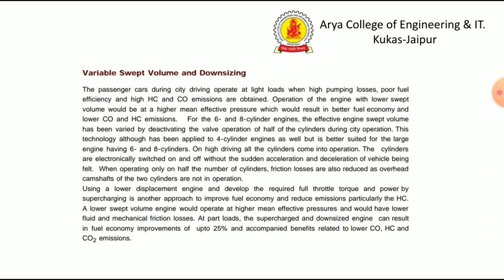For 6 to 8 cylinder engines, the effective engine swept volume has been varied by deactivating the valve operation of half of the cylinders during city operation. This technology, although it has been applied to 4 cylinder engines as well, is better suited for large engines having 6 and 8 cylinders. Using a lower displacement engine and developing the required full throttle torque and power by supercharging is another approach to improve fuel economy and reduce emissions, particularly HC.